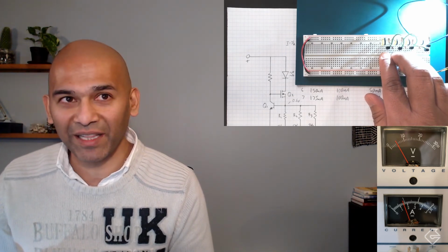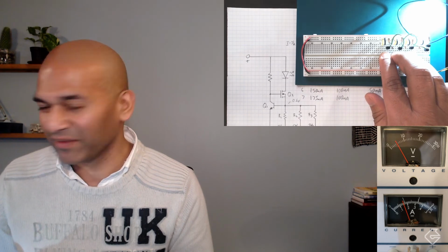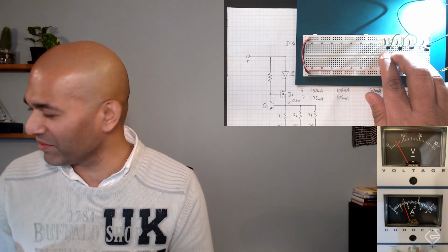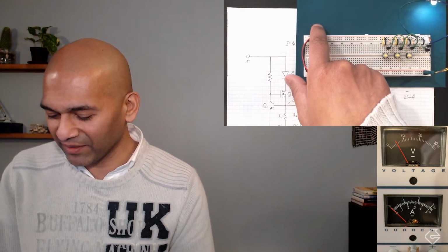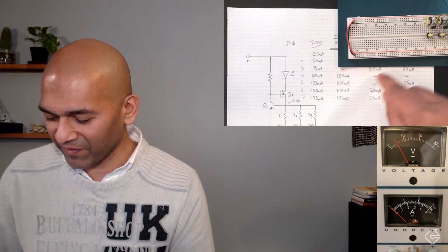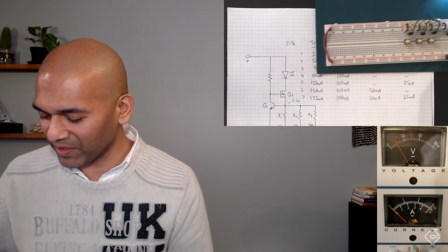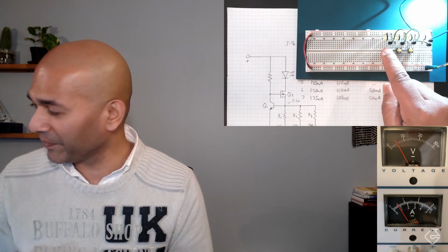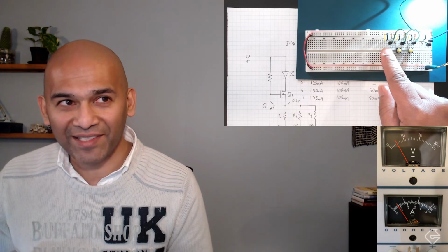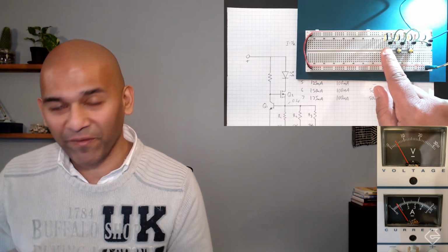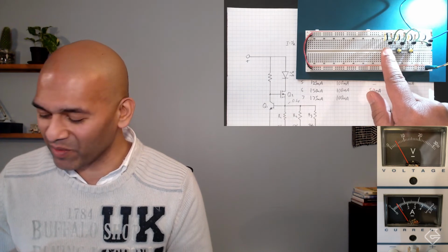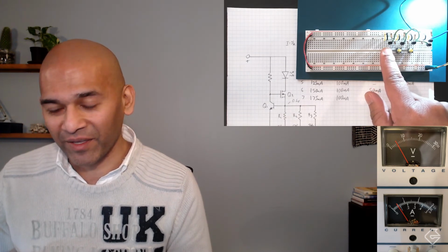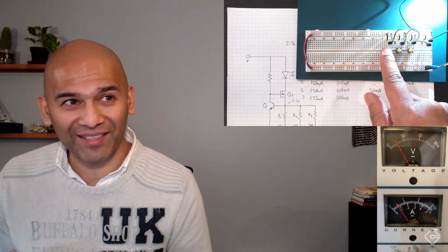It looks to be a little bit less. It looks to be about 150, maybe 155 or so. We're not quite there yet. In fact, if I just do the first one here to get 100 milliamps, just one switch, look at where we're at. It's actually a little less than 100. Now remember, before we should be getting 105 because this isn't actually 6 ohms. This is 6.2 ohms. So we should be getting 105. This time we're actually getting less than 100.